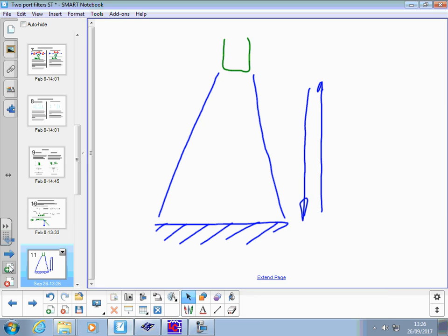But what that has is a beam angle. You can buy sensors with different beam angles so that it doesn't encroach on the sides of your tank or any ladders going up the side.